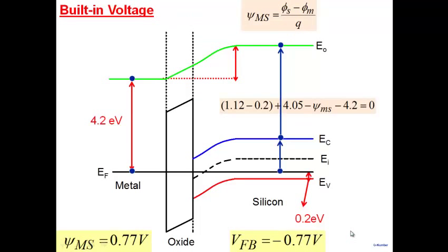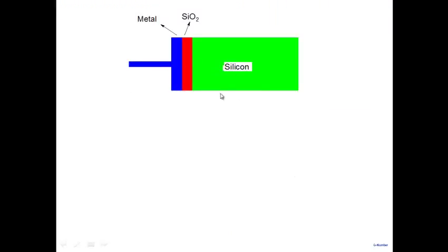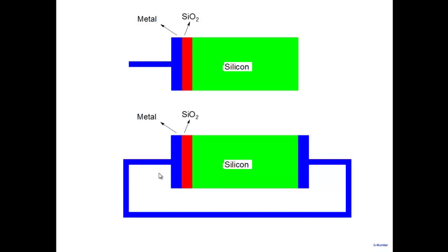All right. Also, I had mentioned that please keep in mind that this is a potential between this point here in the metal and the semiconductor here. And this should not lead to a false impression that I have a system in equilibrium, so how come I still have a voltage across it. We said that you have to keep in mind that this is the diagram that we have drawn. But in addition, what is more realistic is that you have a metal wire which connects the two together. And therefore, if you construct an energy diagram starting from here till here, this is what we had constructed. But along with that, remember, this part is also there. So as we construct this one, we'll see that the drop from here to here is exactly balanced by a drop from here to here. And the net drop turns out to be 0 as expected because we are shorting it with a wire.